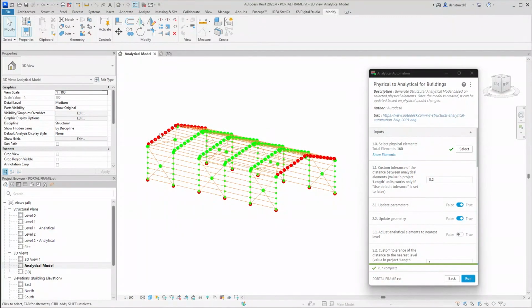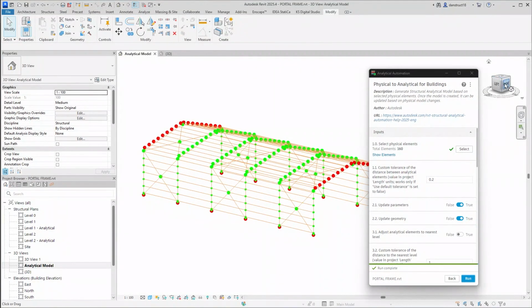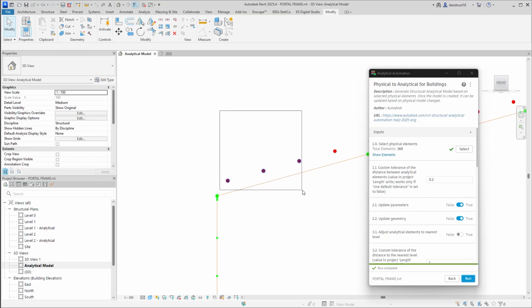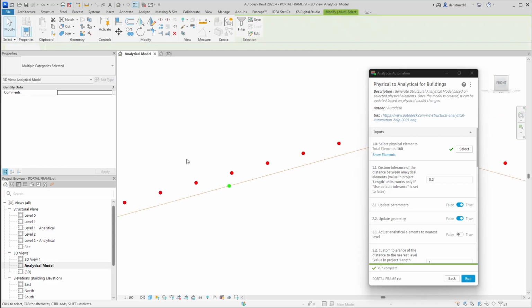Now let's go ahead and adjust the purlins. If I switch here to the front view, you can see the purlins do not rest directly on the rafters. So we want to make sure that they rest directly on the rafters, and then later on we can create offset values in our design software. So I'm just going to make a selection over all those purlins here, making sure that I don't have a selection over any of my rafter elements. So I'll just hold down the control key and select those elements. There we go. Carefully select the elements.